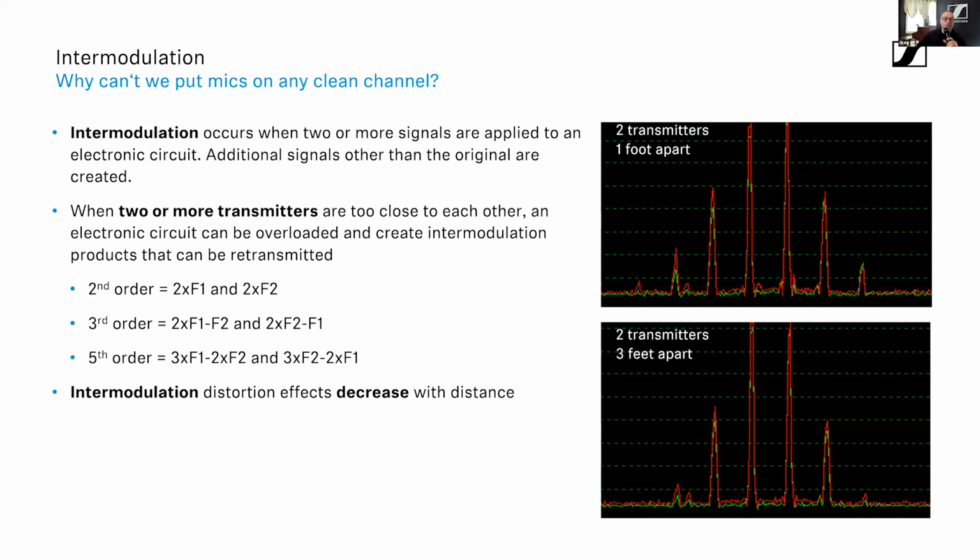I have a good example of this. I was actually at a theater show over the weekend, and they obviously did not do any frequency coordination for their systems, and their systems were susceptible to intermodulation. You're watching the beginning of the show, and the leads are singing and doing their thing, and everything's great. Then the chorus comes out on stage, and everything's still okay. All of a sudden, the chorus members get close to each other. Now they're generating intermodulation, and the lead microphones are cutting in and out. They're dropping out, because they were not placed on appropriate frequencies. It was not calculated out, right?